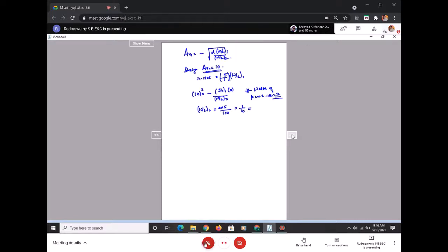Yeah, it's 2 by 20. Is that clear now? Even though it is 1 by 10, we are ensuring that the minimum width of the PMOS should be 2. Length we are not worried about, but we are worried about the width, so that's why we are ensuring it. So even though we are getting 1 by 10, the minimum width of the PMOS should be 2, so we have a width of 2, and the length correspondingly will be 20.